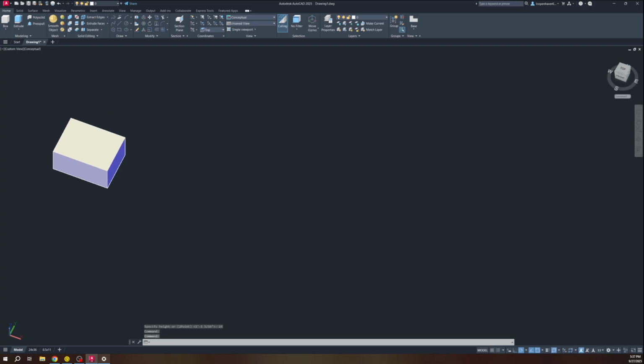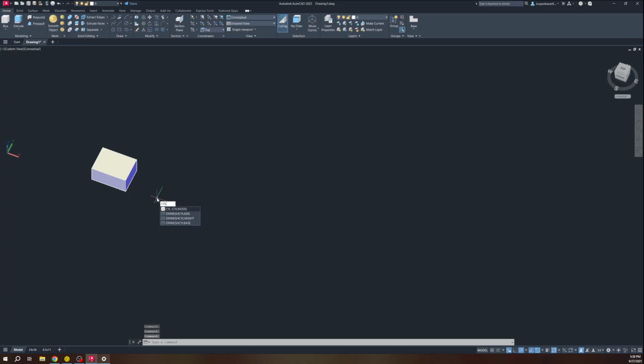I can also create a cylinder, which will be very similar. So I'm going to create the shape that I'm going to then pull into the third dimension, and this is just a circle. It's asking for the radius, so I'm going to make it 12 inches across and then pull in the direction that I want it to. Notice that you can go in either the positive or the negative direction. Doesn't really matter. And let's say that we're also going to make that 3 feet tall. Lovely.